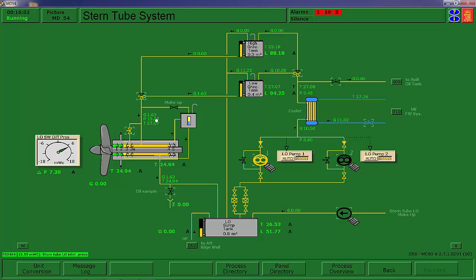In this case, we're saying this is 13.5 millimeters of water pressure. What we're talking about with this pressure, that is set by the height of this tank. And you notice that the tank is overflowing. So this pump is a single speed pump. It is delivering more fluid going in than what is needed.